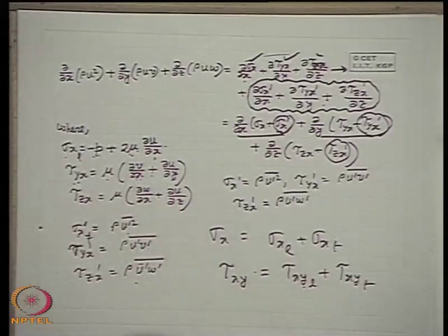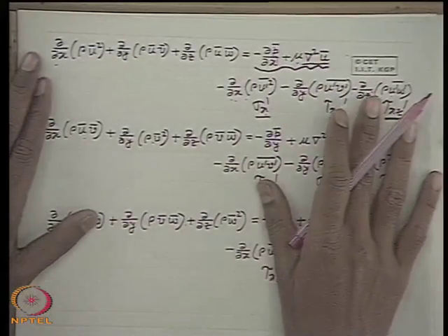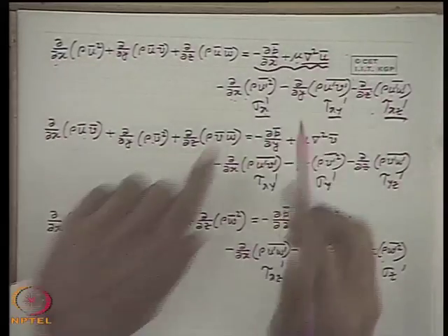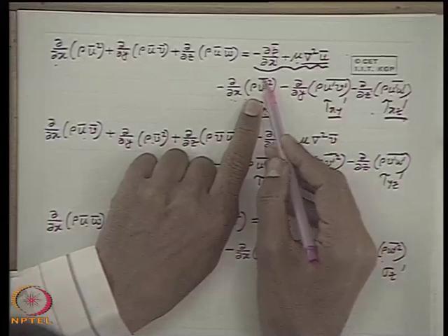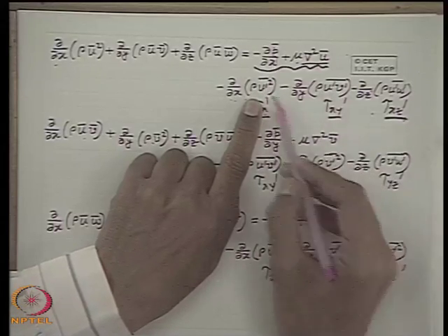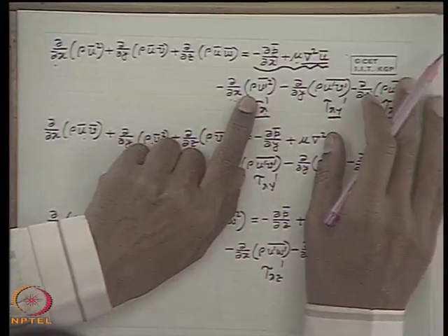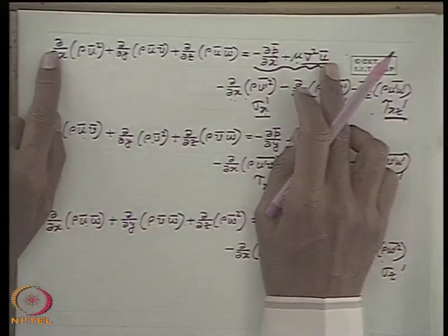This is because, if you look back here, the most difficulty in integrating these equations to find the flow field is the occurrence of this fluctuating component. Because of the erratic behavior of the fluctuating components, or its random fluctuations with time, we do not know an exact mathematical formula of this velocity component with time. So, it is very difficult to integrate this equation.